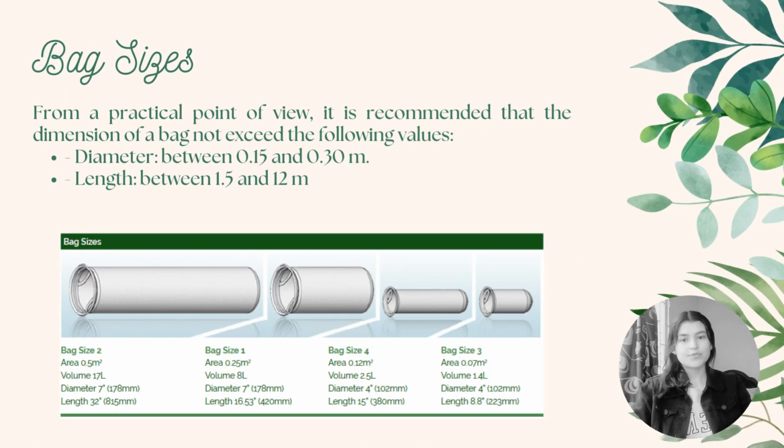Bag sizes. From a practical point of view, it is recommended that the dimension of the bag not exceed the following values: diameter between 0.15 and 0.30 meters, and length between 1.5 and 12 meters.